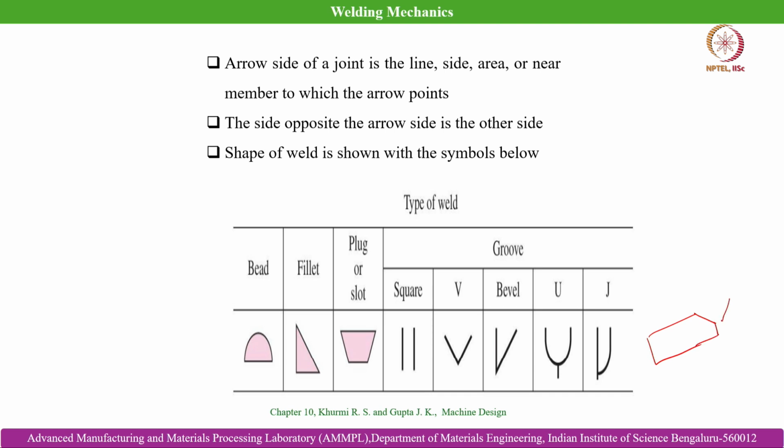we discussed that butt welds can be classified in terms of the joint architecture. In spite of the name, a butt weld is not always a V groove joint. It can be of other shapes, like a typical U shaped joint preparation, and then we call it a U type butt joint. It can also be prepared as a bevel shaped one, or a J shaped grooved one.